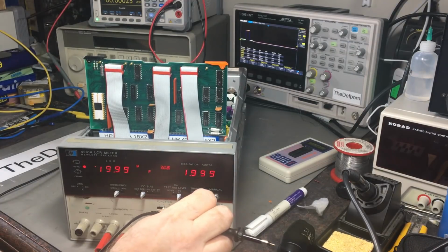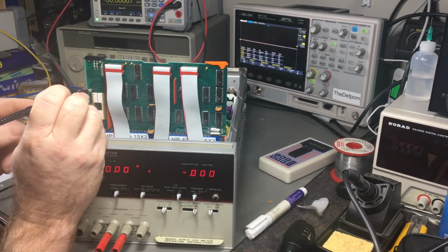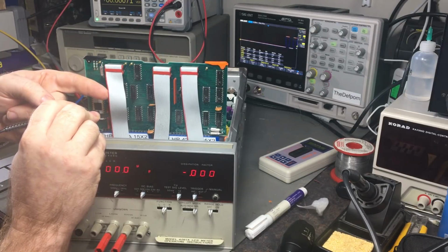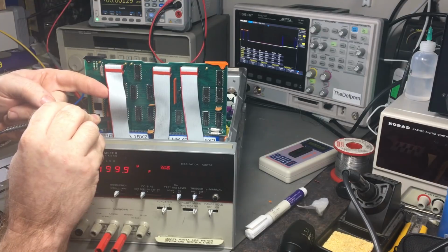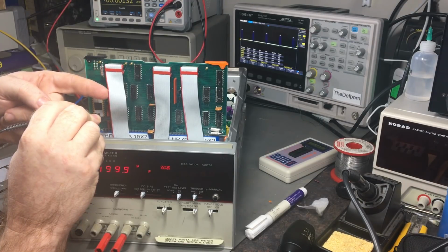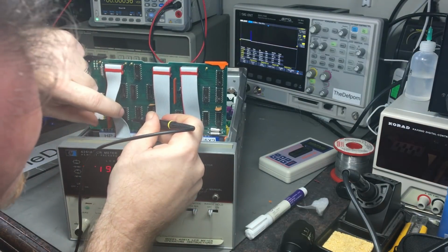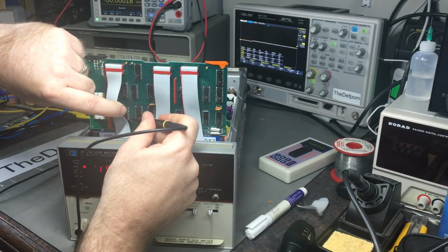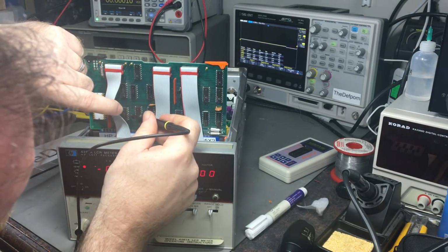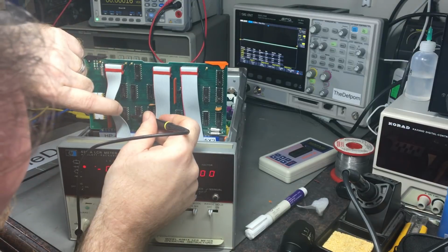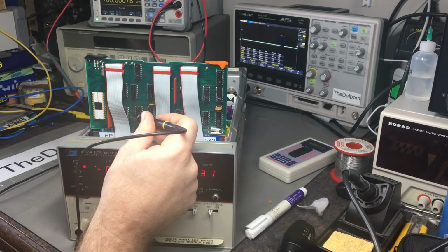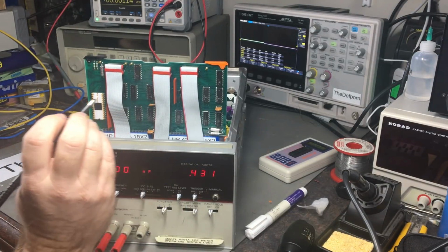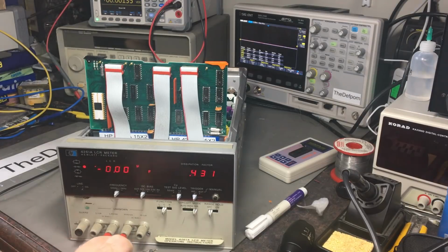I've got the same test again in serial or series. I'm recording everything because some people may want to reference this. So in series it should be going high and low, that's correct. Pin 8 should be low, apparently. It is. And pin 10 should be going high and low as well. It is, just much slower. That's okay. So that's the capacitance shorted out.